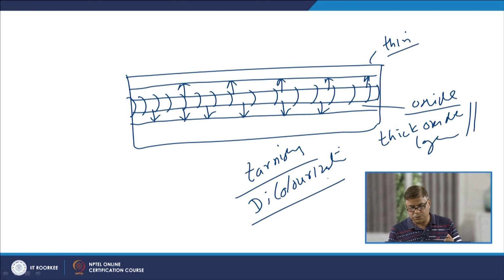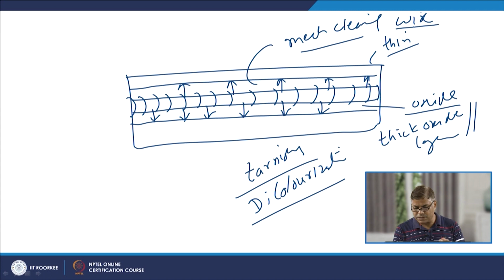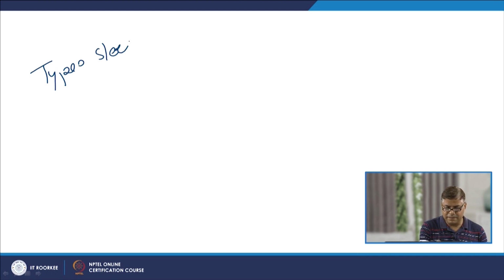In order to restore the shine, this additional or thick oxide layer which has been formed next to the weld zone, or next to the region which has been heated, has to be removed by mechanical cleaning using a wire brush or any suitable means, so that the earlier shine can be brought back.